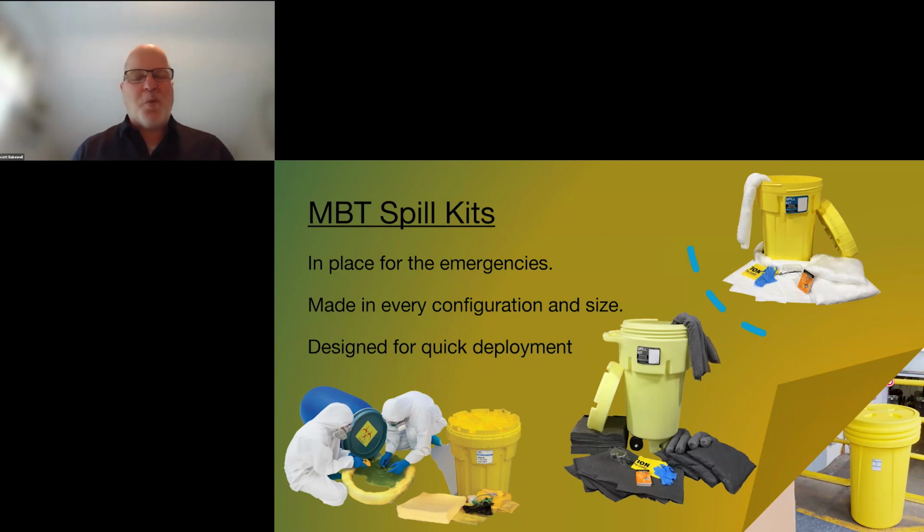A lot of times when we're walking through facilities, and I'm sure you folks know this as you're running these facilities, the spill kits are there. They look like they haven't been open in a while, and when we spin the lid off, you'll see half of it's gone. A lot of times guys will go in there quickly and maybe grab 5 or 6 pads, go back to their machine rather than going to the regular sorbent stock. They kind of go through the emergency stock.